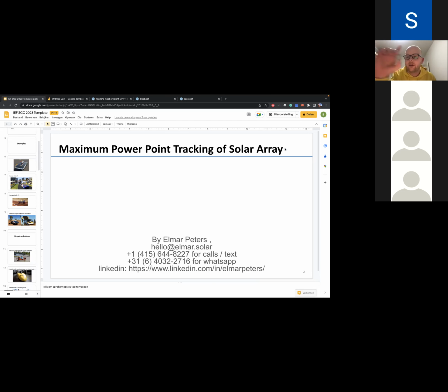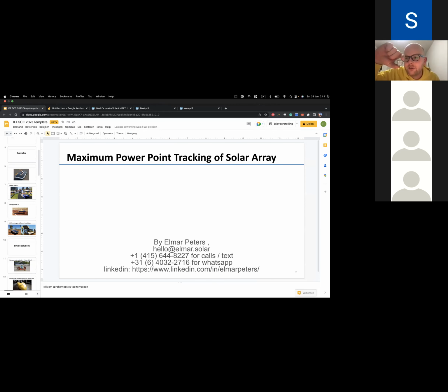Also, I found a buck converter that goes from 48 volt to 0.6. Wow. If you do that the other way around, you can boost one solar cell to 48 volts. That would be wonderful. But it's made for server power supplies, and it can output 0.6 volt at 300 amp. So you can just put all your solar cells in parallel and connect them to this. Right. It's only like 96% efficient, I think. Well, just something to think about.